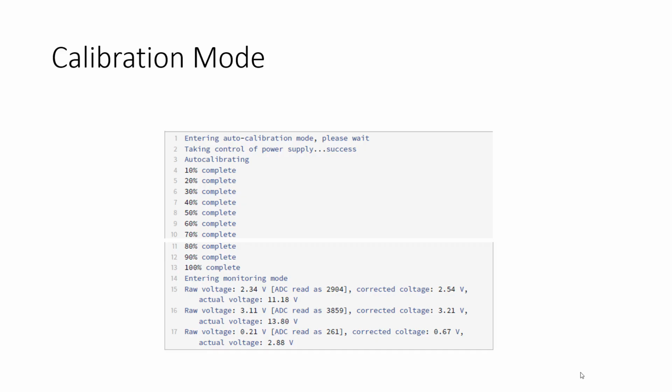Use VBAT and ground. We're not connecting anything to 5 volts here because the 5 volts is supplied by the USB connection to the computer, so you don't need to connect anything to 5. The VBAT is designed to be the 12 volt battery. If you wanted to run this without a USB connection, you can by connecting a power supply to the 5 volts. If this were being used in our standalone motor-based project, then we would be supplying the 5 volts for the ESP32 and the 12 volts for the motors. We don't regulate 12 down to 5.